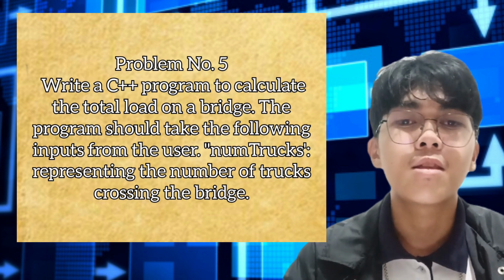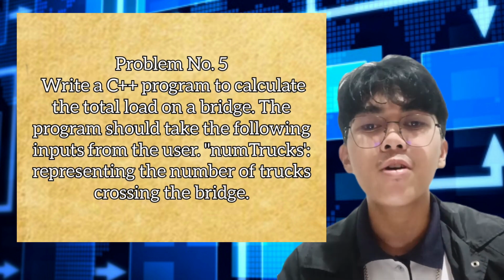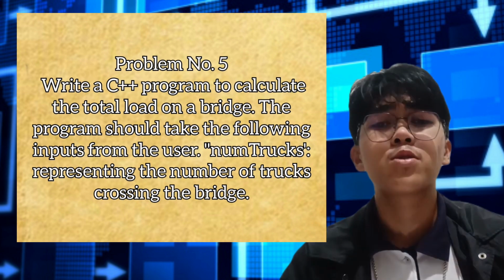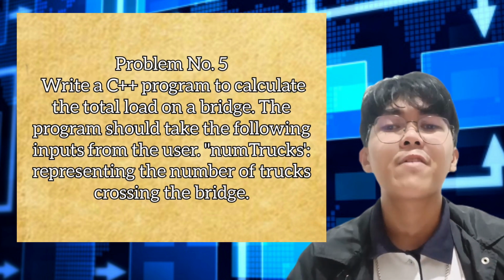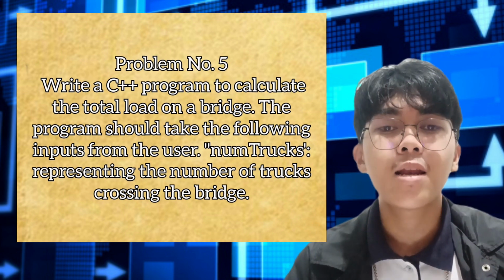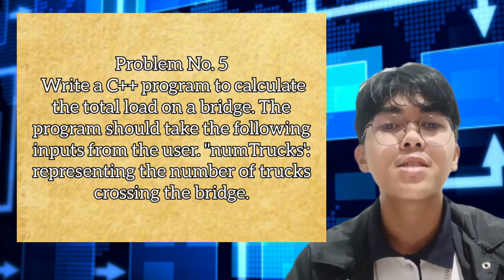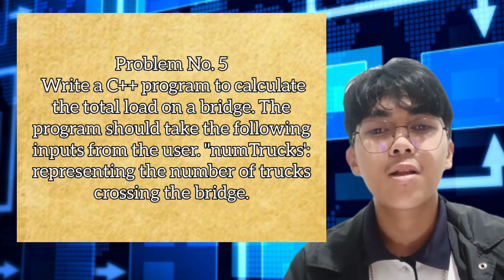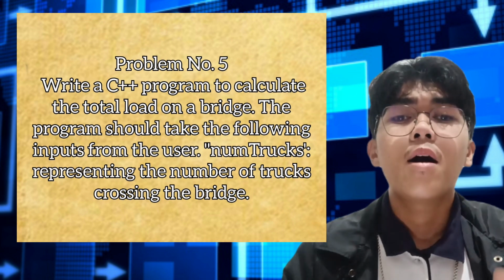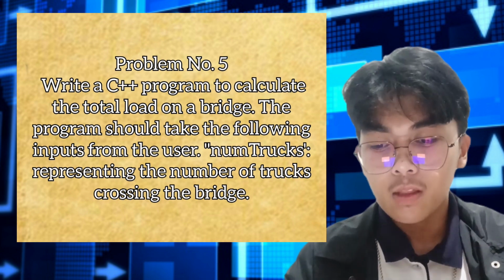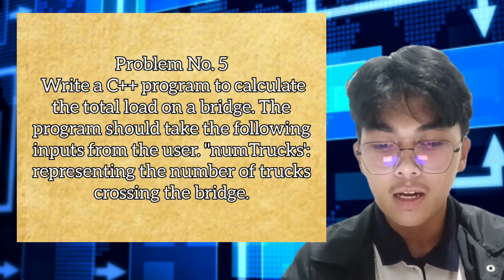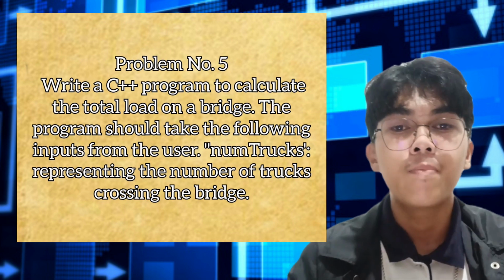On the other hand, the truck axles represent the number of axles present on that particular vehicle. It is important for us to know that axles greatly affect the weight of a particular vehicle because they greatly affect the load on a particular vehicle through suspension. Additionally, we are to assume that the following load distribution factors of the vehicles are based on this concept.